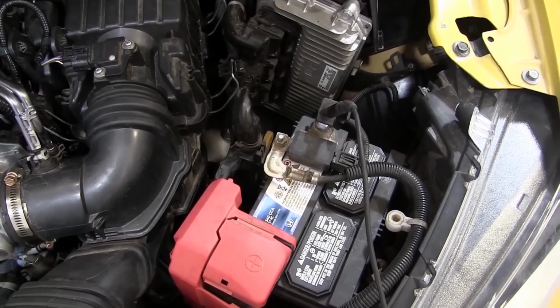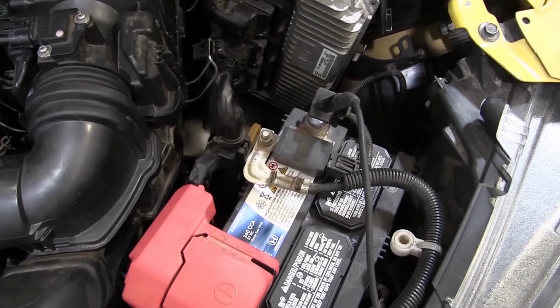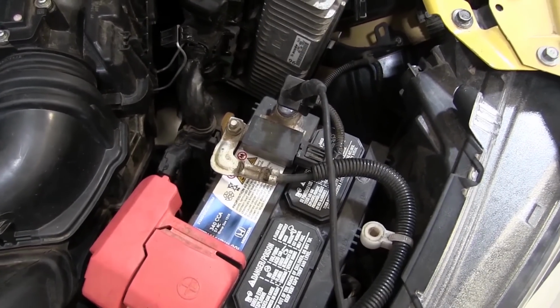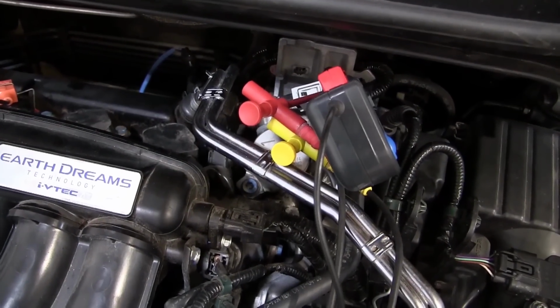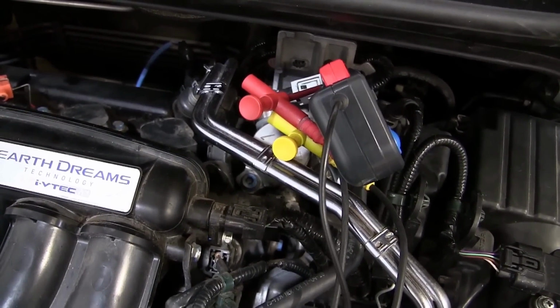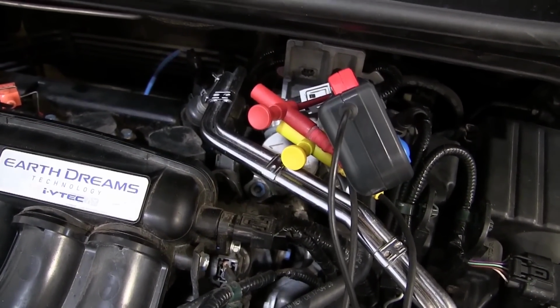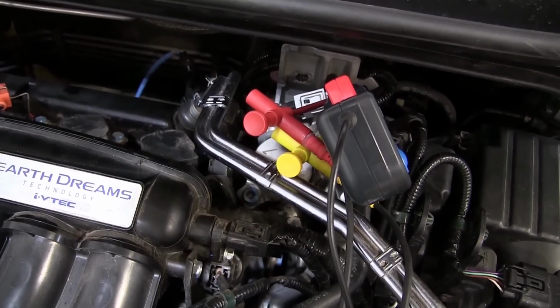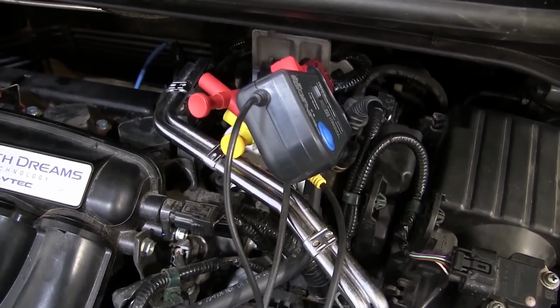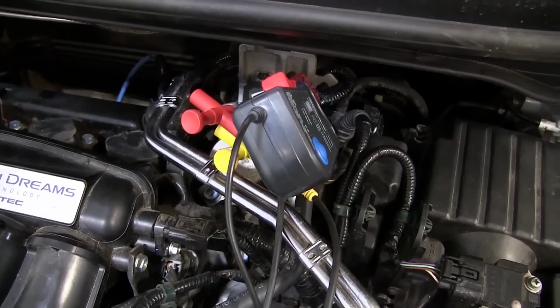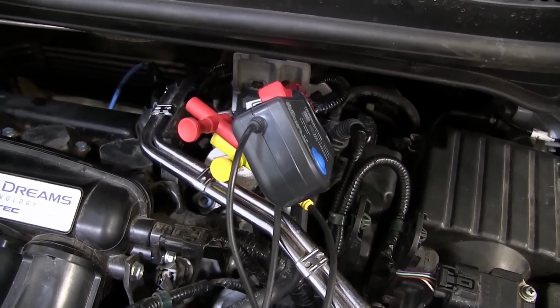Okay guys, let me show you how I got my oscilloscope connected. I've got the oscilloscope ground connected to the battery ground. This is a high pressure regulator. I've got channel 1 yellow and channel 2 red connected to the control circuit for the high pressure regulator. I've got channel 3 green connected to the current, so we can see a current clamp on channel 3 for the high pressure regulator.